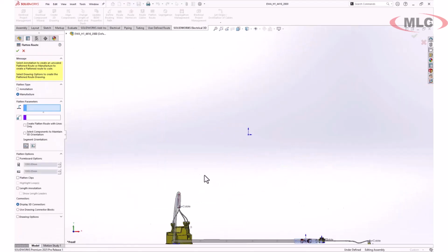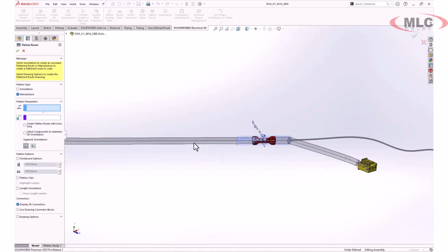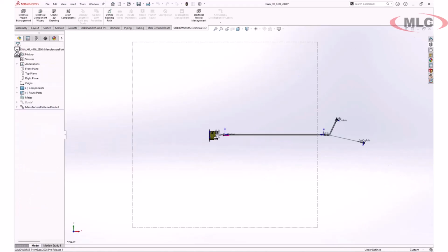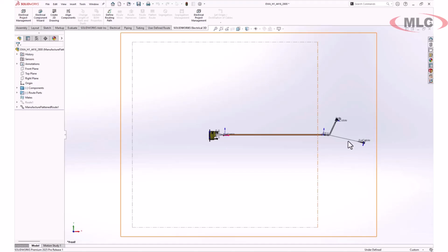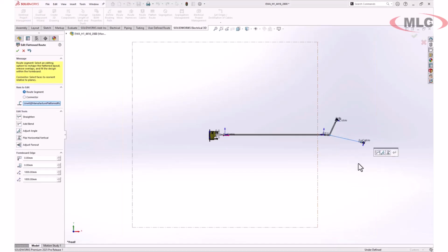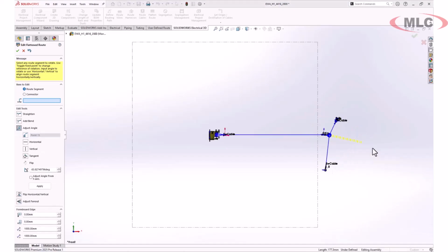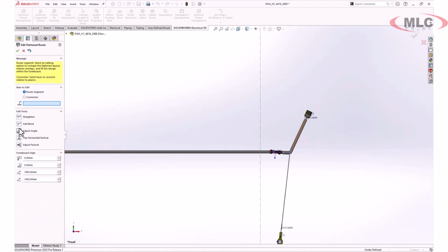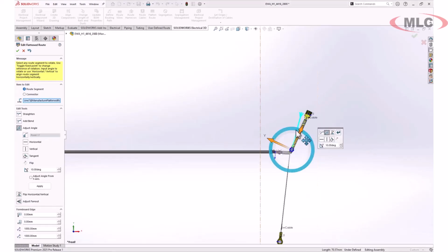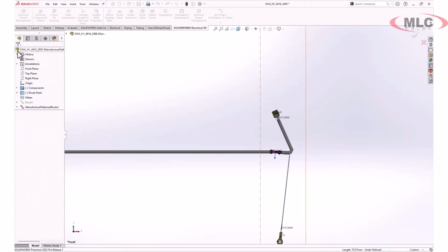The Flatten Route tool also offers improved support for complex and multi-circuit splices. For example, identifying the junction points and loop segments and moving them to the flattened plane. In previous releases, the editing of Flatten Route has been improved. You have to try this on-screen interface for making these fine adjustments to the flattened route. Even with this significant change to the harness, the drawing updates better than ever.